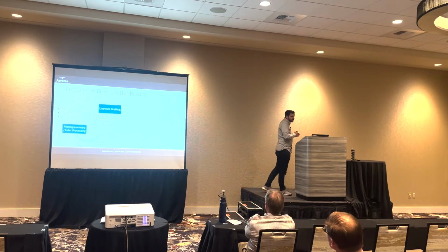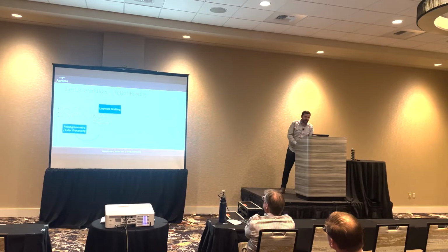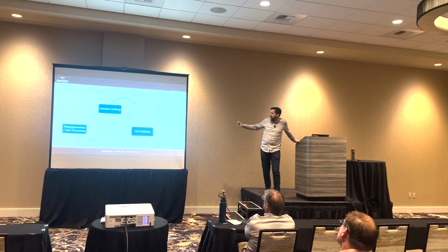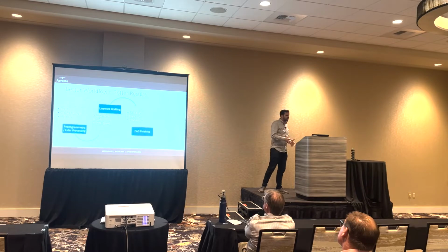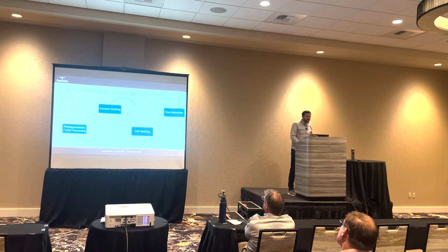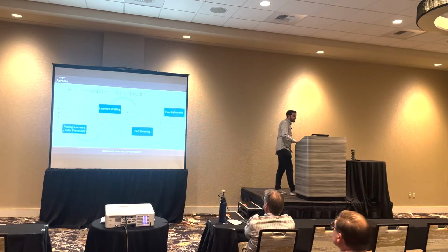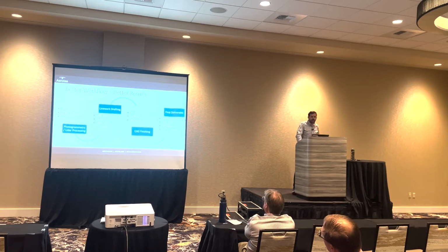Civil 3D or anything. Then it goes through what we call the line work drafting phase, which is when you actually turn it into vectorized features: your 3D points, your polylines, typically in a DXF format or one of the less rich data types. Then you go through CAD, where you actually create your final TIN surface. You create your contours based off of that. You integrate all of your other non-drone related data that's already there. Add in your site culture, everything from labels and symbols and blocks to street names, typically in a DWG format, and that's what gets you your final deliverable.